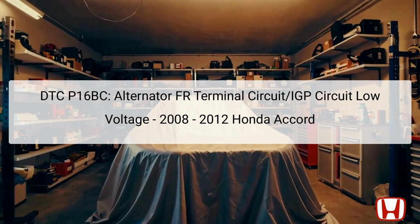Today, we will be discussing the specific Diagnostic Trouble Code DTC P16BC related to the 2008 to 2012 Honda Accord. This code signifies a low-voltage situation in the alternator field relay (FR) terminal circuit or the ignition power (IGP) circuit. The alternator plays a crucial role in the electrical system by converting mechanical energy from the engine into electrical energy, thus charging the battery and powering the vehicle's electrical components while the engine is running.